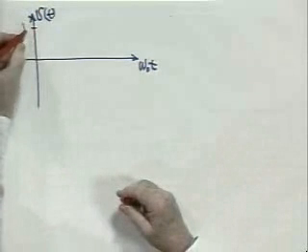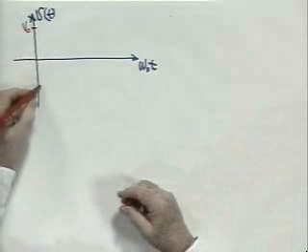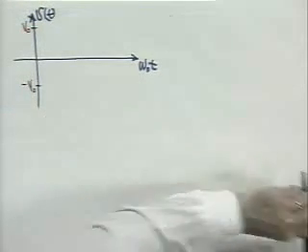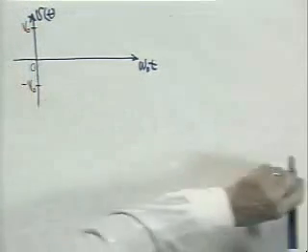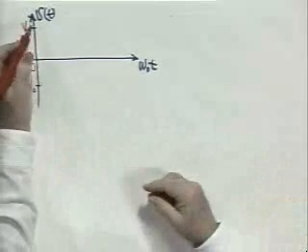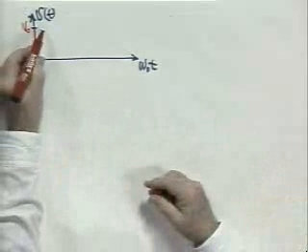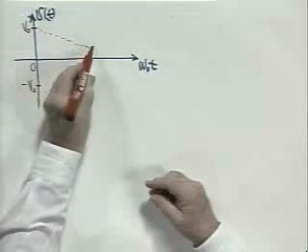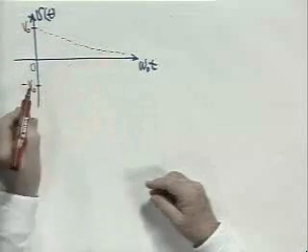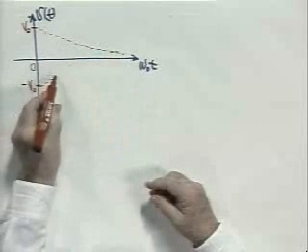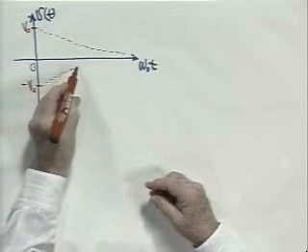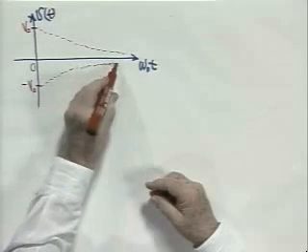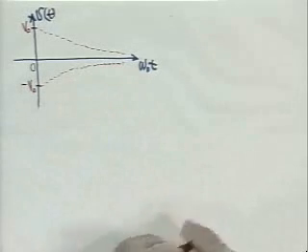And if I sketch here V0, and down here an equal distance down minus V0, this is the origin. These exponentials, which decay towards 0, provide an envelope into which the cosine function must fit. This is plus or minus V0 e to the minus alpha t, so it's supposed to be symmetrical.